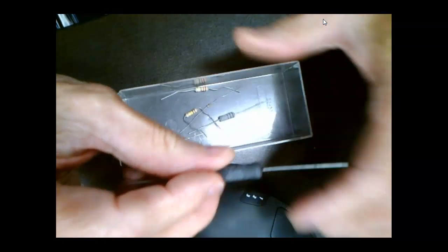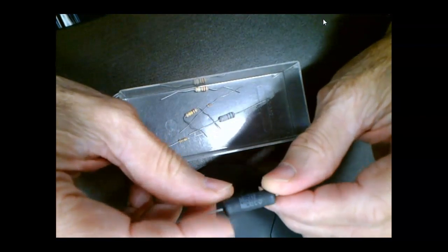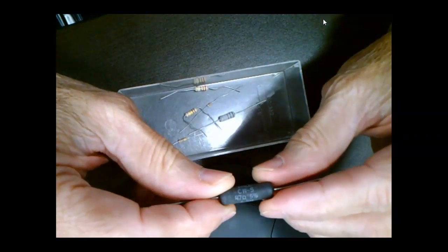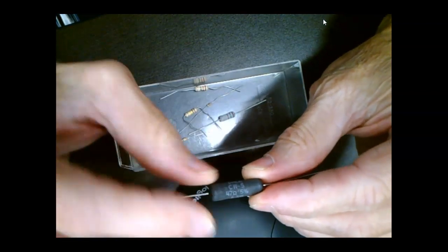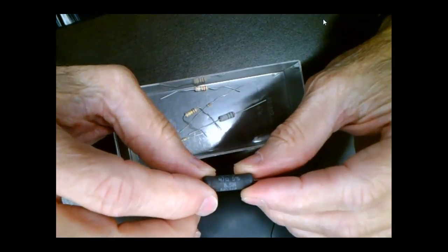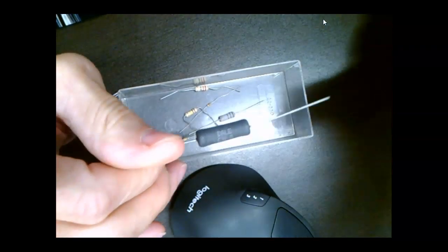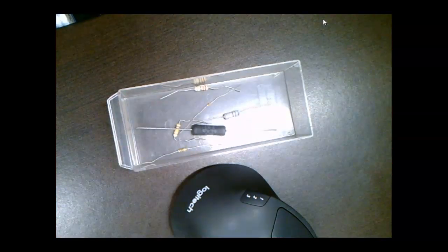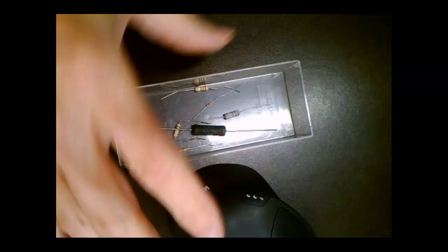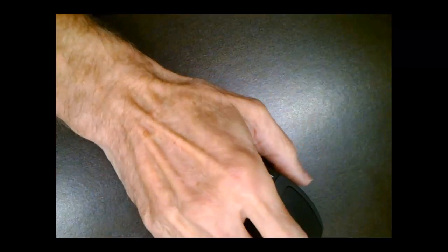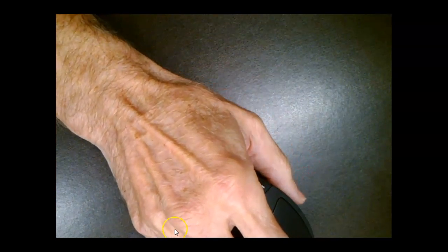Once we get into the higher wattage ratings, a lot of the resistors get really big. And since they're big enough now, instead of using color codes, they just write it on it. So this is a 47 ohm resistor, and it's a 6.5 watt resistor. So the higher the wattage rating, the bigger the physical size of the resistor has to be. Sooner or later they stop using color codes, so they just write it on there. Here you go, Matt. And it goes right up the line, and I think we got it all the way up to a 2 watt in there.